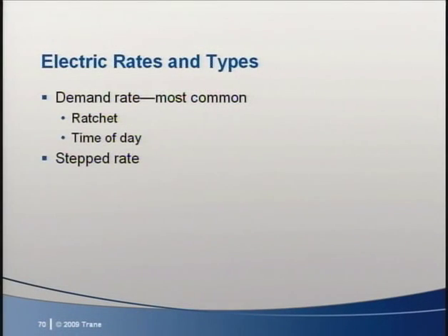Stepped rates can also be good for storage. They can be tricky to evaluate because we tend to look at them like a typical demand rate. Most times, the published demand charge in a stepped rate cannot be thought of or compared to a demand charge in a conventional rate. The actual, or as I call it, the effective demand charge is not obvious. For example, a stepped rate in Georgia has a published demand charge of $6.83 per kilowatt. Is it really?